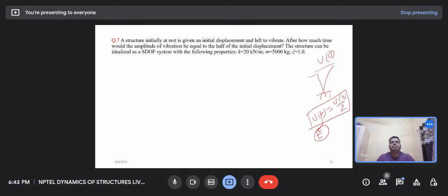So do you know what the solution is for the critically damped system? Mainly we are focused on the case of the underdamped system. And do you know any example of where we use the overdamped system? Door closure. Yes, in door closures we require the overdamped system, where we want the response to decrease slowly and there are no oscillations.